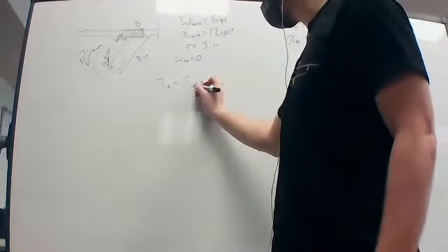So A relative to O is going to have the same omega and alpha as the wheel because it exists relative to the wheel's center. So that's important to note. And we know that this radius is 2 inches. So right away we can say AT is equal to alpha R. So alpha 12 times R, that's 2 inches, so 24 inches per second squared.